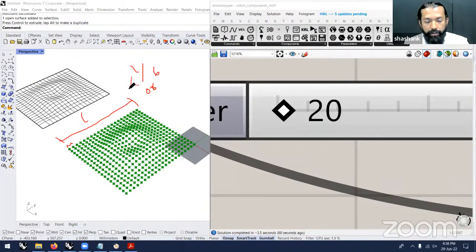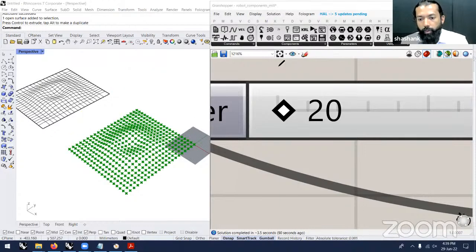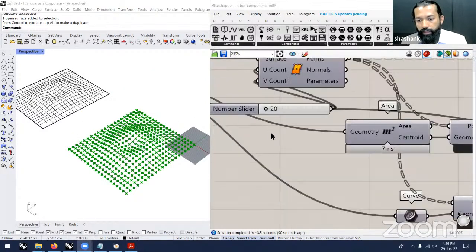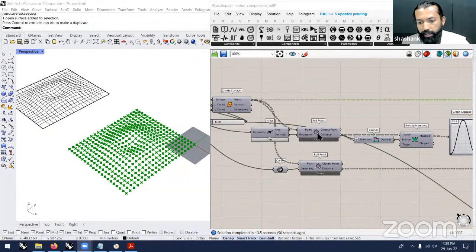You're going to have that value, say I'm going to call this y, less than L by 6, so that with the number of iterations you have, you can create sufficient overlap, and all the remainder material is cut. And once that is set, you can move into dividing it by the geometry.